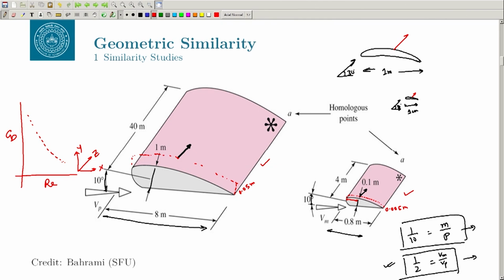Now, you might ask the question that the Reynolds number is a function of many different parameters. Rho u L by mu, as you must have read in your fluid dynamics course: density, velocity, length scale, and viscosity. And CD is basically D by half rho u square, and maybe L square also if you divide by area.